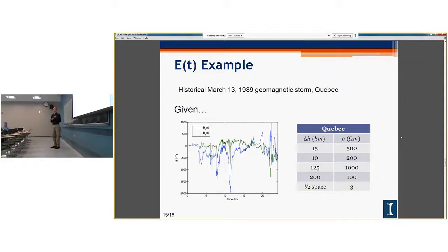I think it misrepresented the fact that this actual potential in the Earth doesn't change. It's the loop that's created by Faraday's law when you have a closed circuit between the conductors and the Earth that induces a source that's modeled in the actual power lines themselves. So, no, I don't think that it changes how we view the Earth as being equipotential.